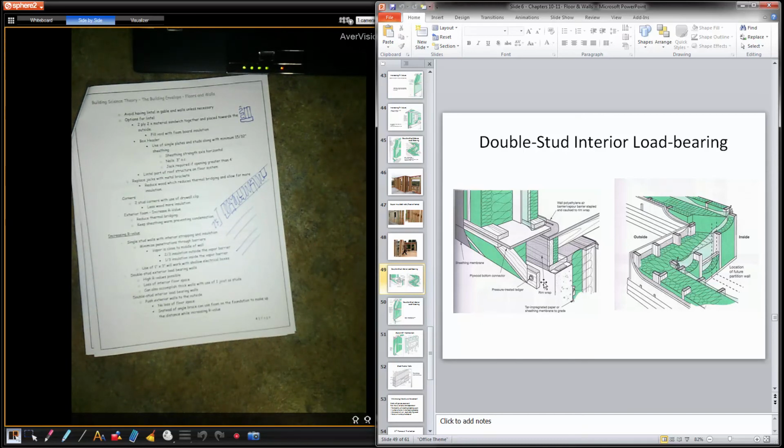A lot of passive homes do basically this. They'll actually have the wall stick out. Underneath this wall would be foam, so like maybe an 8-inch. That's probably closer to 10, maybe 10 inches of foam on the foundation to then make the foundation warm, and then make it look like it's all continuous.